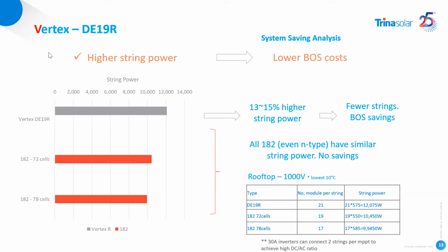It can maximize the AC/DC ratio of the inverter, giving at least 4 to 5 more modules per string. This means you can maximize the space and lower the cost of everything in the BOS: cable, stringing,